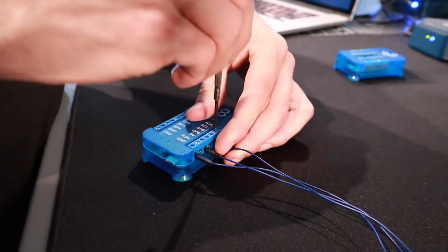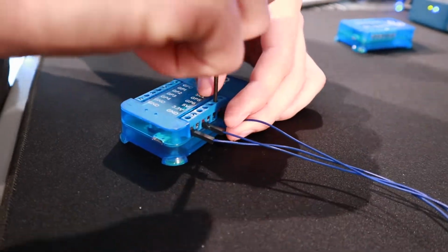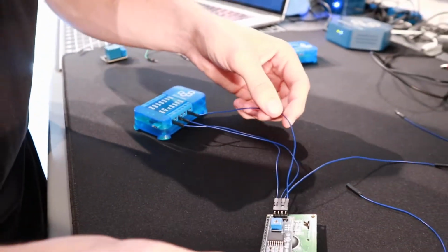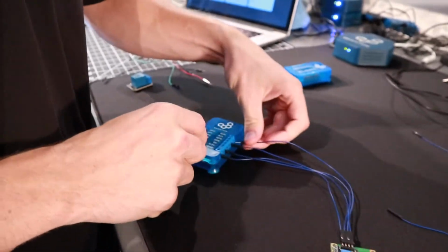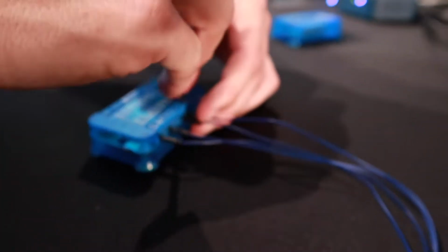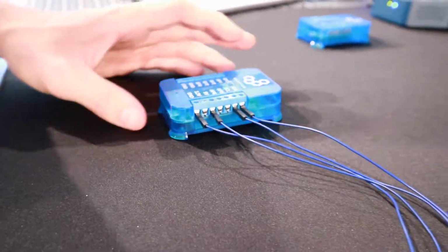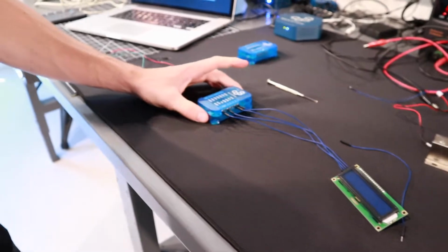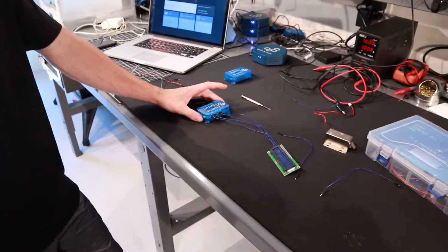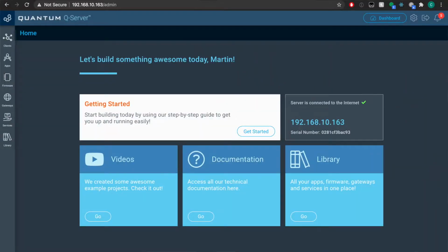So this display is going to use I2C, right? Yeah, it'll use I2C communication. And then how do you get the address usually? With any I2C device on our system, you can just connect it to the client, and then you can go into the debug properties listed under the clients menu.